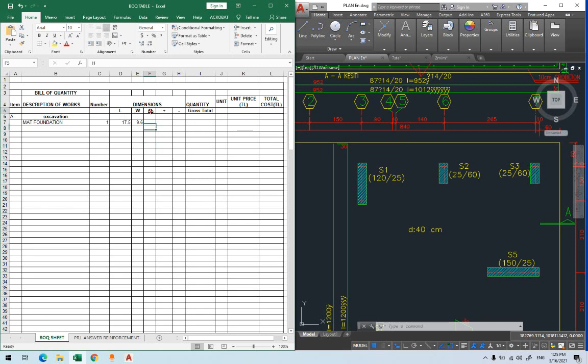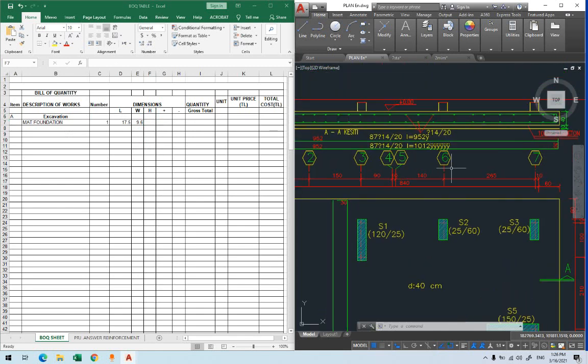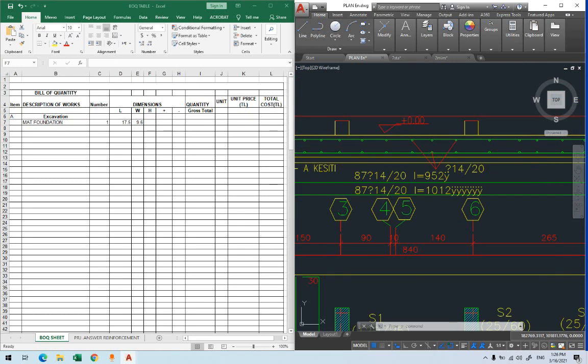Now when it comes to height of excavation, remember, this is excavation, not the footing. So we want to calculate the depth of excavation here. How much we have to excavate? We need to know the ground level and the level that the excavation will be. Now we said on the excavation something will be given like this, 0, 0. So this is the top of the excavation.